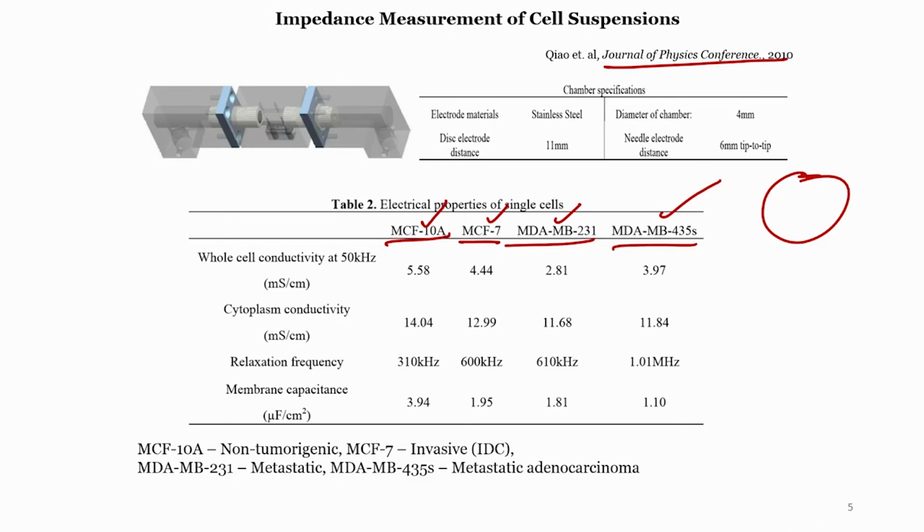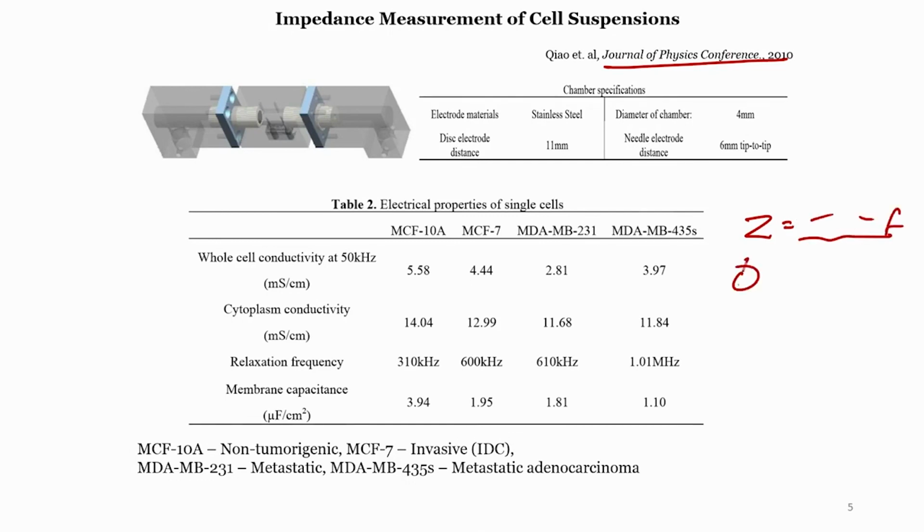So these people have tried to measure the specific properties of a single cell by measuring its bulk impedance and then resolving it. When we measure the bulk impedance and we also get the phase angle, then Z cos phi and Z sin phi are what we can use to get the individual contributing components. Or alternatively, let us say we measure the impedance of a single cell, and we know the mathematical formula for the transfer function of the electrode and the cell interface. Then our transfer function will have some frequency dependent terms, and the phase also will have some frequency dependent terms.